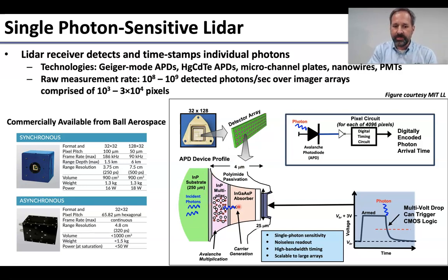It comes through the substrate, goes into the absorber region, and some is absorbed there. Now, the idea here is that you bias these avalanche photodiodes slightly above what's normally considered the breakdown voltage. And here I'm showing this voltage that we just kind of touch it a little bit, tickle it, and bring the charge up the capacitance slightly, a few volts above this breakdown voltage.